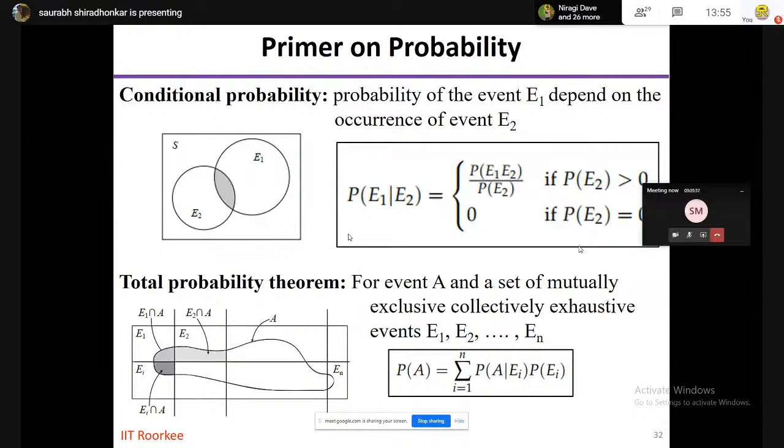Then the next theorem, which is very important, is the total probability theorem, which gives you the probability of happening A, across various different events, using this particular formula, which is again an extension of conditional probability. And why is this important? Because in the lifetime of a structure, even if we say that we are designing for one particular earthquake, another earthquake, even though its intensity is less, is also possible. So here E1, E2, E3 represent the possible earthquakes that could cause damage to a structure. It couldn't be the same damage, the collapse damage. It could be some other state of damage as well.